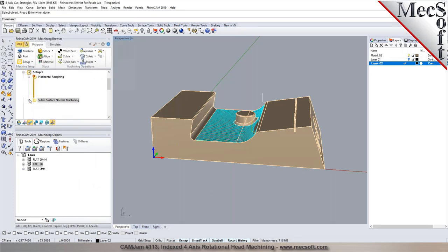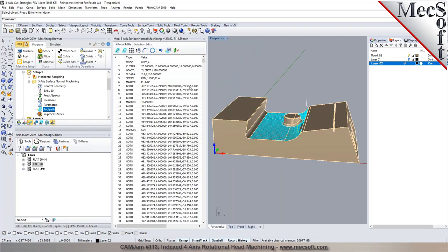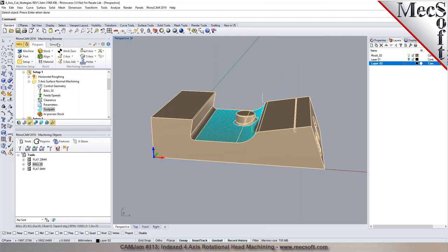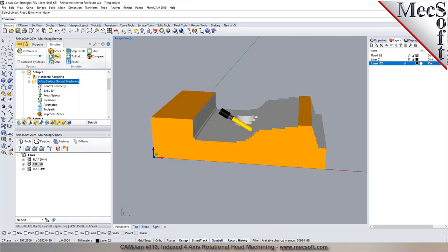And then generate the path. You'll notice that the secondary axis angle is changing. You see -59, so it's constantly rotating. Your B is rotating as you're cutting it. That would be in the Premium configuration. I haven't put in any collision or gouge check against the sidewall. Oh yeah, I understand that. If you need the continuous rotation of the head, that would require the Premium configuration. That's the difference between indexed versus continuous, where it's able to move all 4 axes simultaneously.